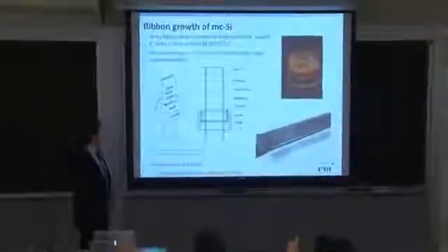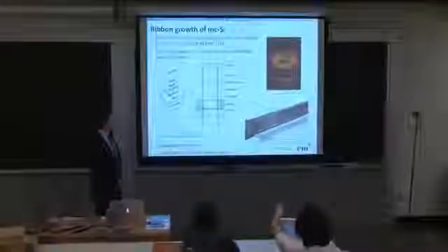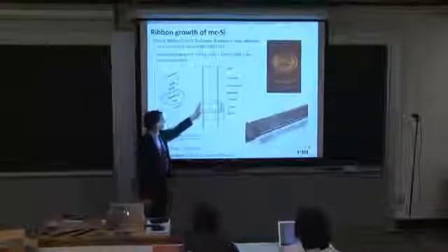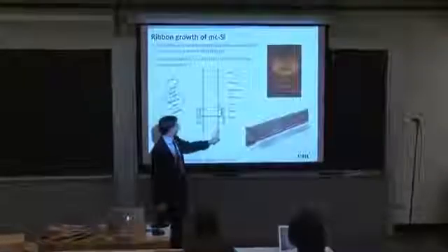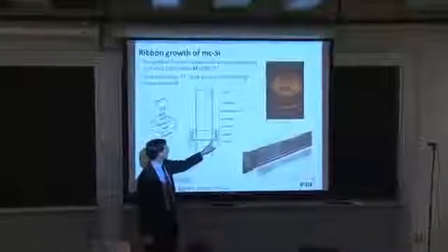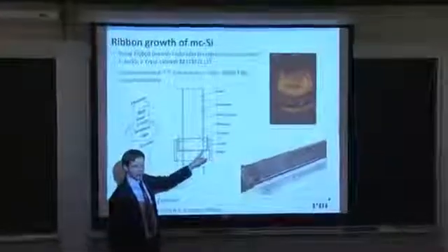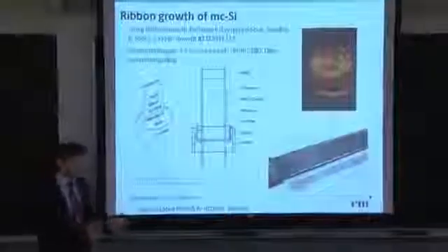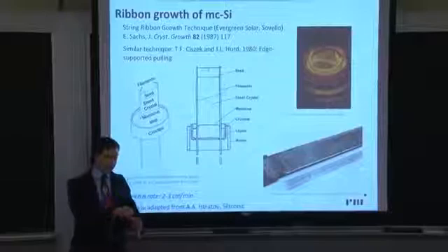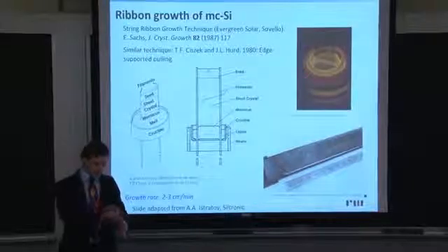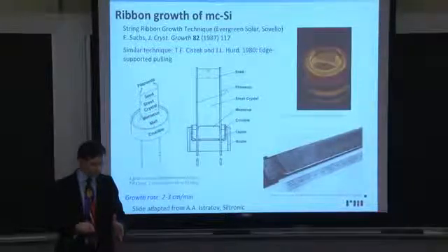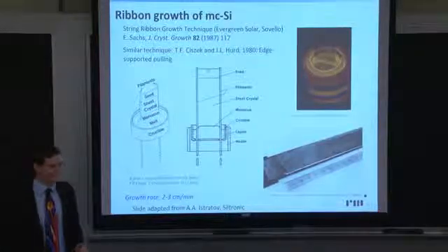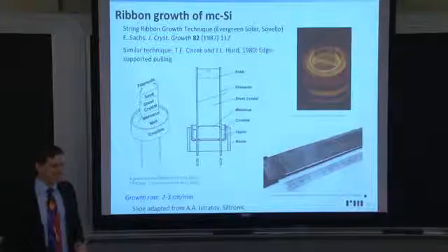OK. How do you seal the space between the filaments and the bottom of the crucible? Right there, right? Since this is your graphite crucible right here, and these are your filaments popping up through the graphite, the beauty is you don't have to seal that. The surface tension of silicon is greater than that of water. So if you've ever filled up water to the top of a glass and seen that meniscus that forms, the silicon meniscus would be even higher than that. Oh, that's cool. Yeah, it's pretty nifty. I'm imagining this like molten metal. You don't want that spilling out the bottom. But that's really cool. Okay, cool.